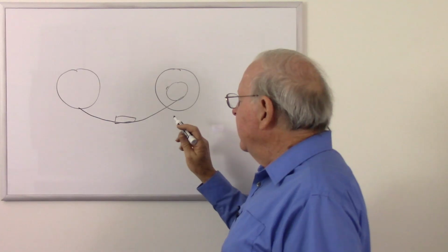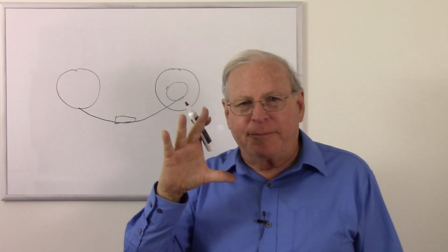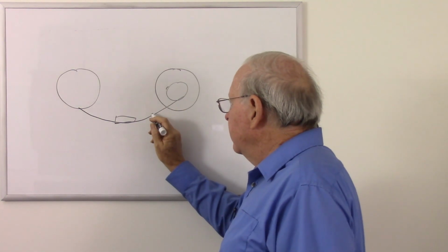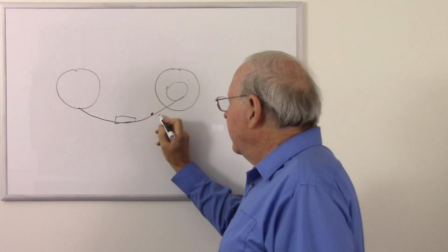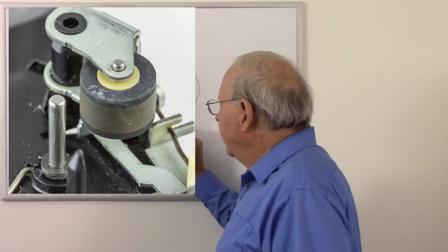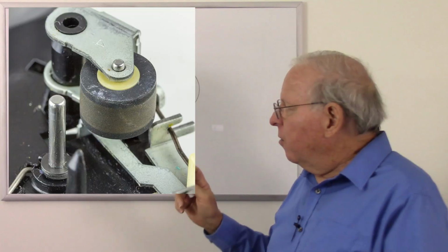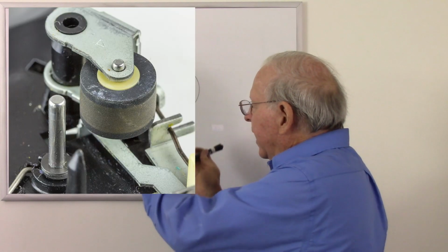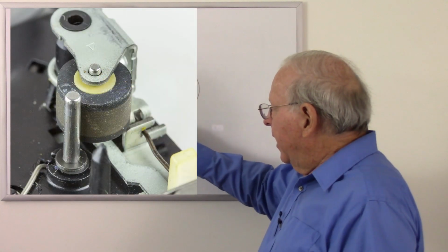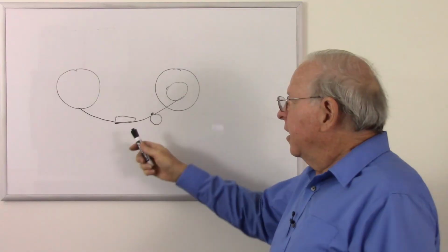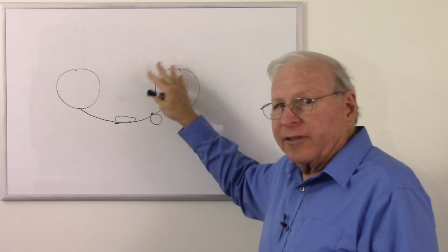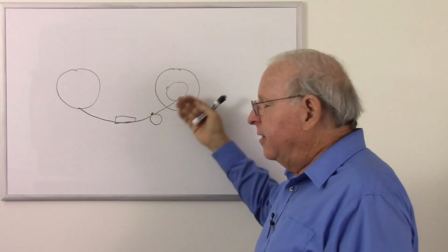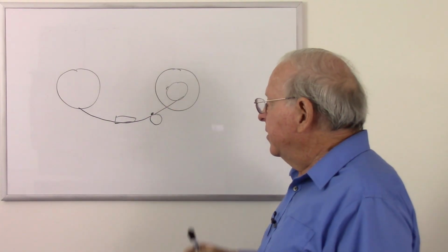But any decent tape recorder is going to have what's called a capstan drive, where they have a metal cylinder, probably somewhere right around there, and then a rubber pinch roller. And when you were playing back a recording, these would come together and pinch the tape and move it at a steady speed across the heads. And then the take-up reel just had a clutch on it, so it took up as necessary rather than being the impetus for moving the tape.